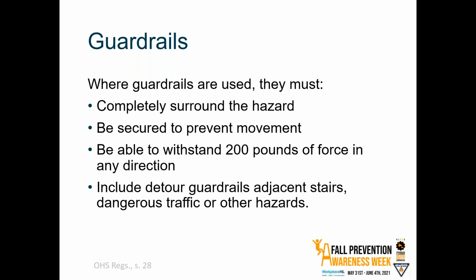The swimming pool was empty, and around the deep end of the pool, they had placed guardrails to make sure that workers wouldn't fall in, because again, the pool is empty. However, these guardrails were not secured to the floor because of the tiles around the swimming pool. They didn't want to damage it. As a result, during a toolbox meeting, someone leaned on these guardrails and fell into the pool.